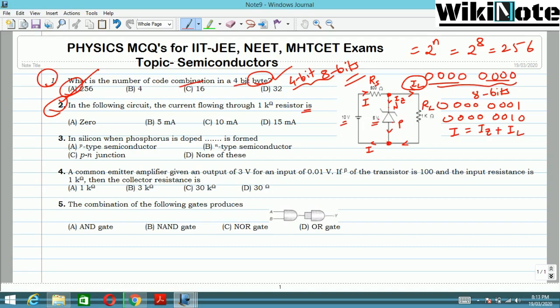So the voltage across the Zener diode will also be treated as the output voltage, because I am getting the voltage across this, so that is going to be my output voltage, and output voltage is Vz, which is fixed, and which is equal to IL into RL. So load resistance and the current flowing through this, and current flowing through this is IL as already stated, and this is IZ.